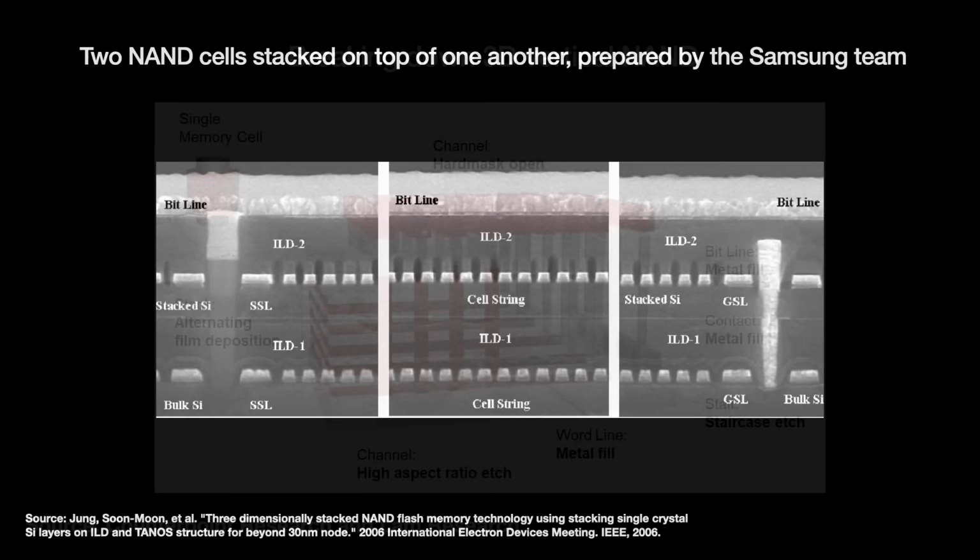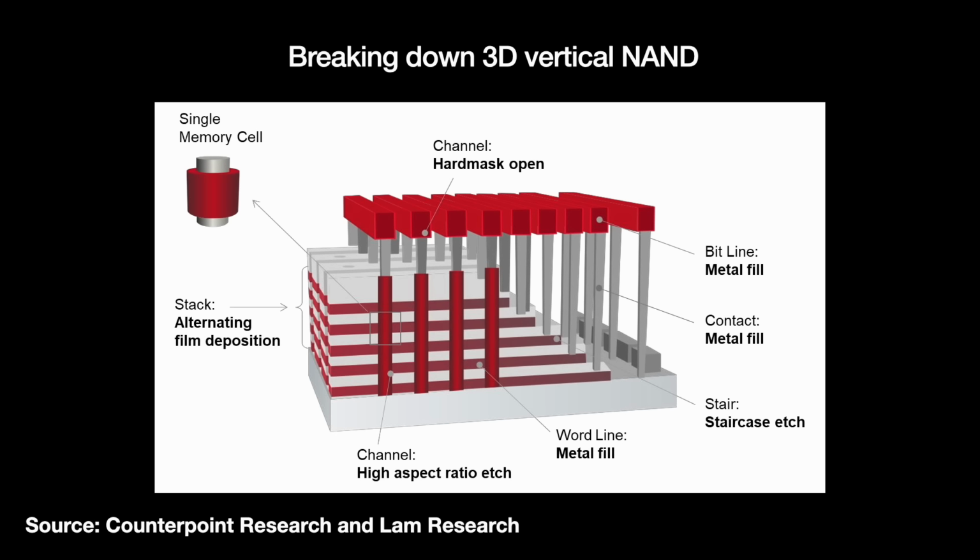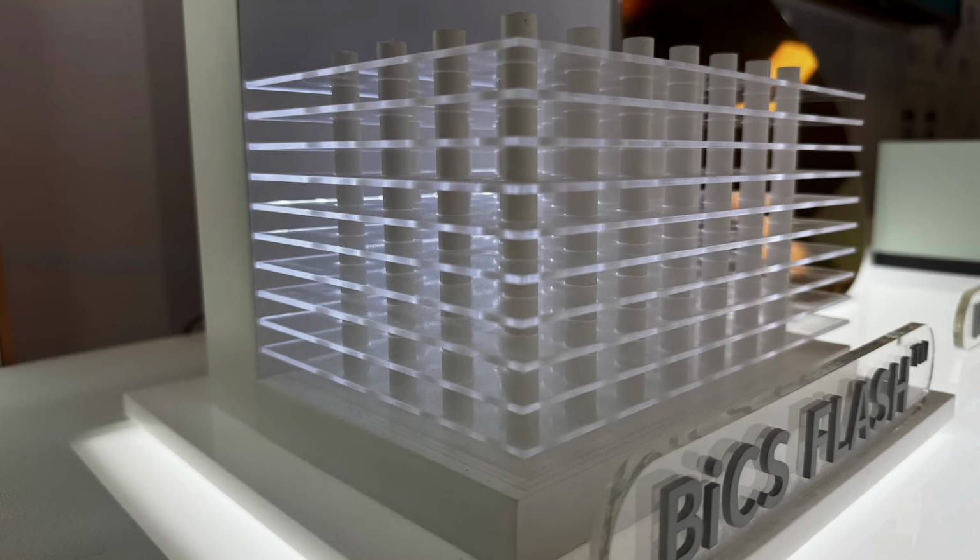Memory makers eventually moved to stacking alternating layers of semiconductor material on top of one another like a lasagna. These will be the word lines. Then you punch circular holes through those layers and deposit dielectric and metal inside the holes. Your nodes are where the layers and holes intersect, like doors in an elevator shaft.